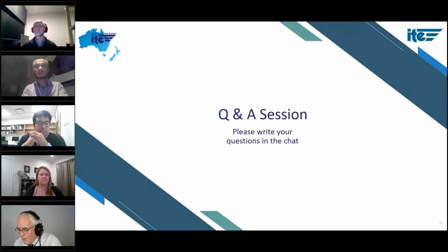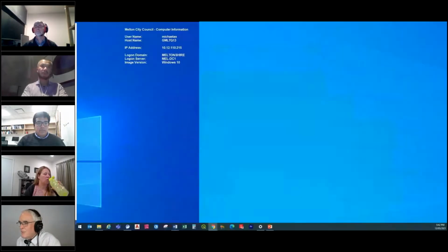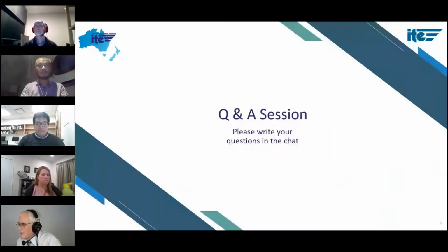I know the presentation mentioned autonomous vehicles. We don't know what that's going to do to things like gap acceptance and saturation flow. Some people think it might be better. Some people think it might be worse. So as time goes on, we need to keep looking at the defaults, but what is in there at the moment we think is pretty good. And that's probably the best you can do if the intersection doesn't exist yet.